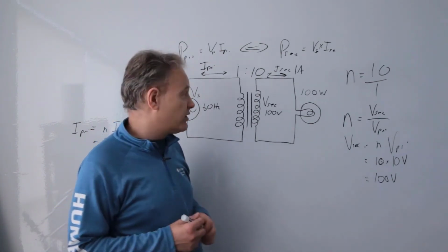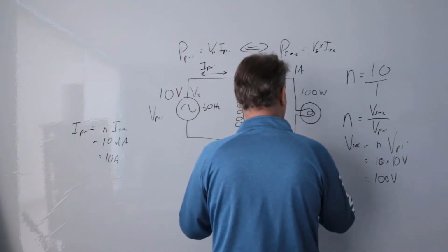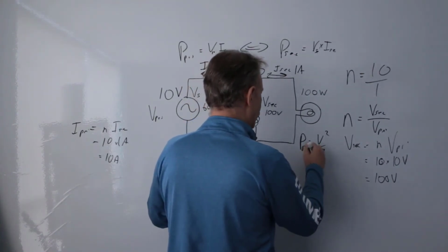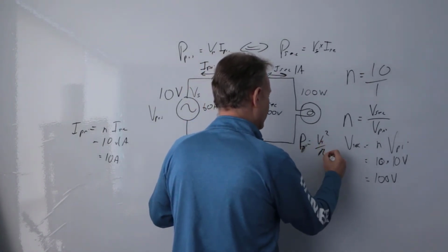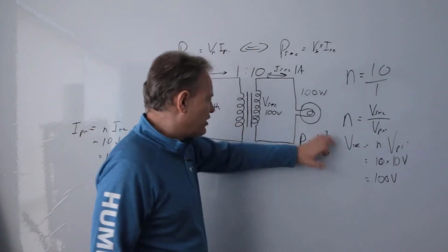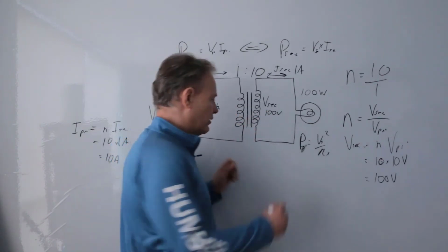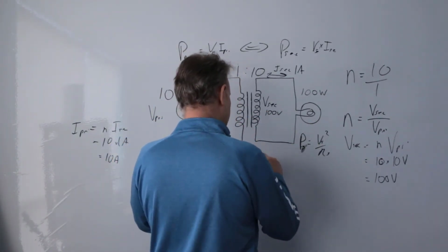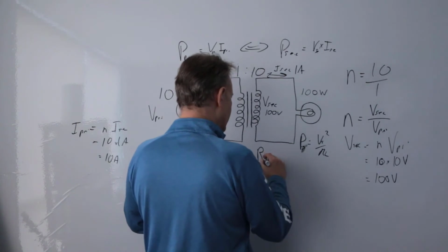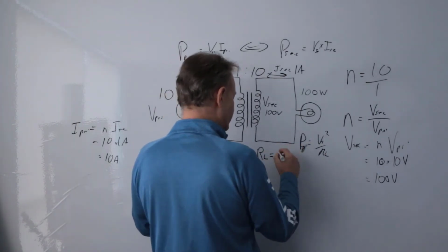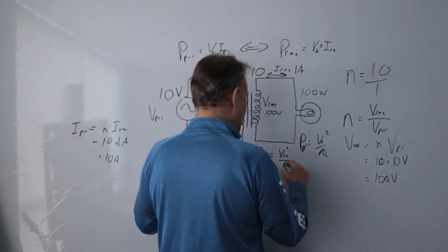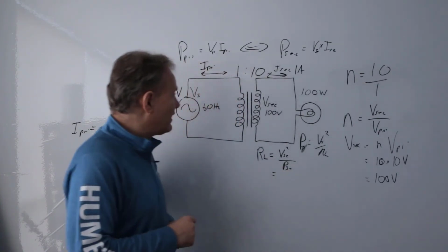So we have a couple different ways to do it, right? We know that power equals V squared over R, with my secondary values, and then I could solve for that, or I could actually use Ohm's law here. Let's actually use this one because I've already used Ohm's law in an example. So I'm going to rearrange this, and I'm going to say the resistance of the load in this case is going to be the voltage secondary squared divided by the power of the secondary.